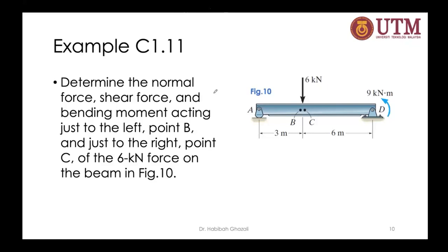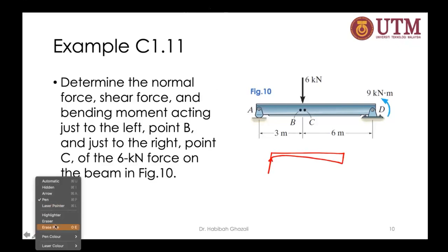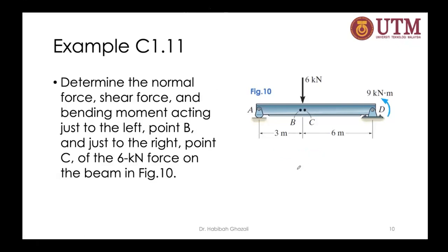Okay, so for this question, the first step, you should draw the free body diagram. If I draw that free body diagram, I know that this is a roller support. Good job. So this is a roller support. You isolate the member from the rest of the world, and I have a roller support here. It will prevent it from moving in the Y direction, but it's not going to prevent it from moving in the other direction, and also rotation.